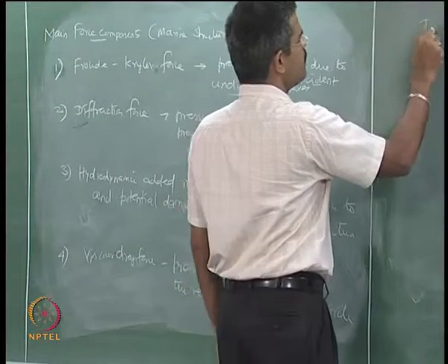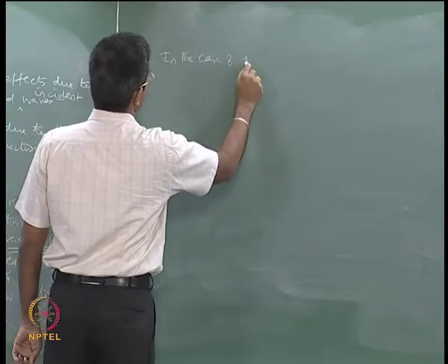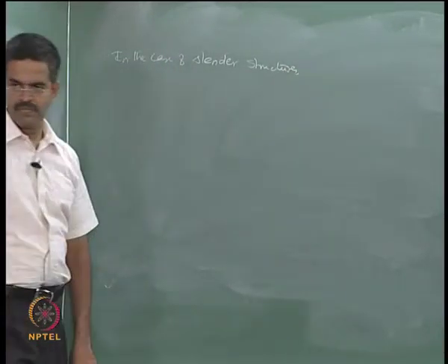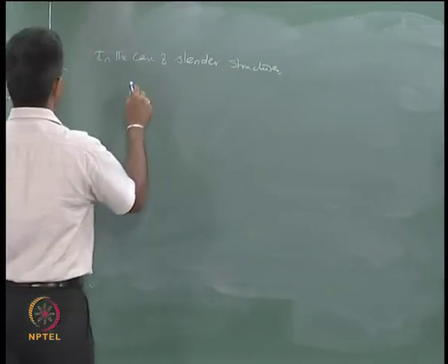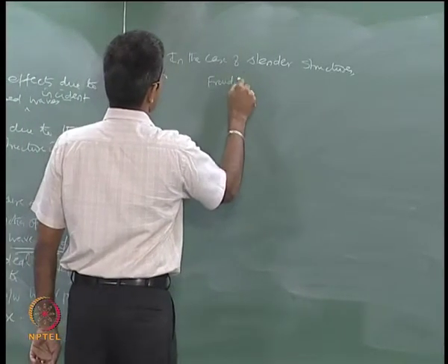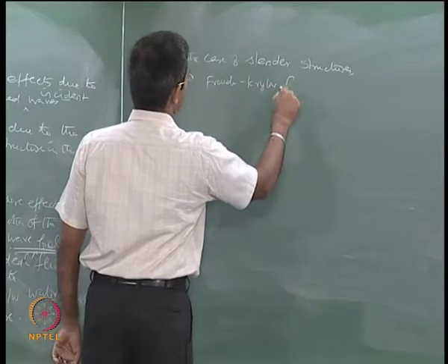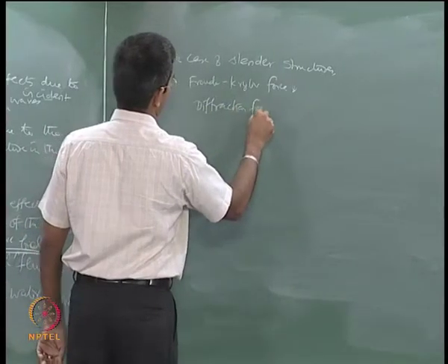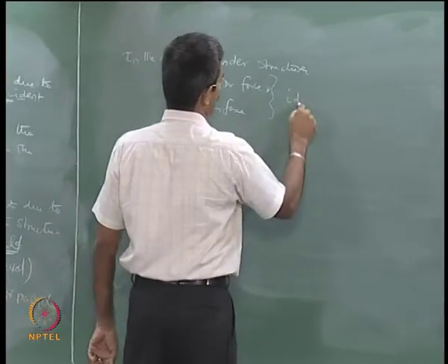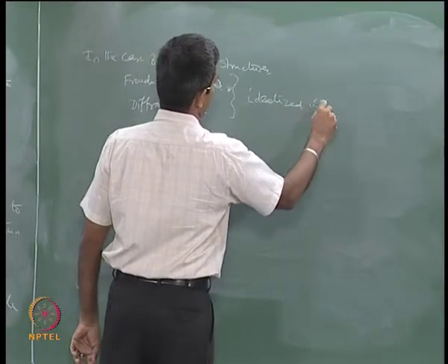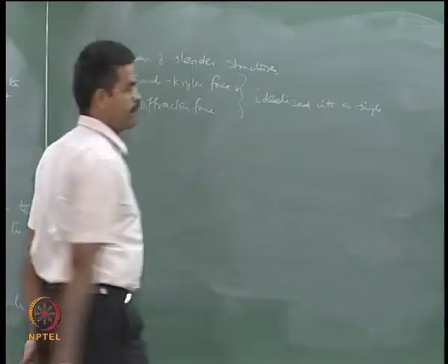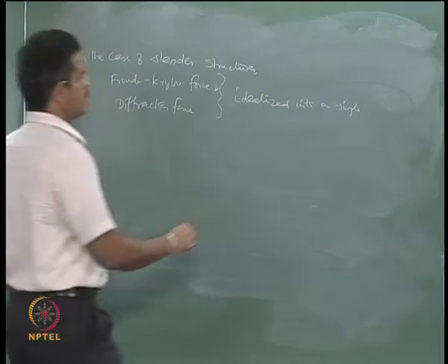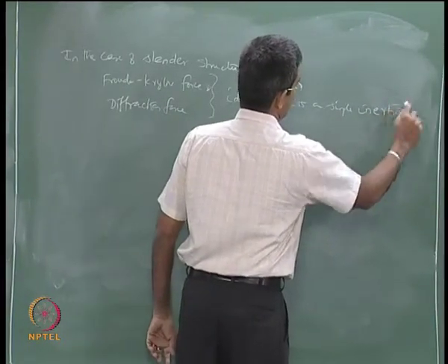Now, interestingly, in the case of slender structures, the Froude-Krylov force and the diffraction force together are idealized with a single inertia term.